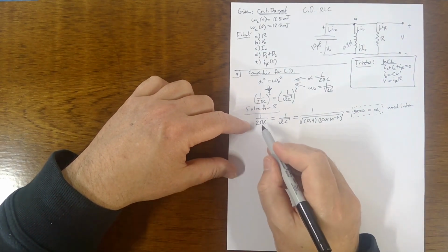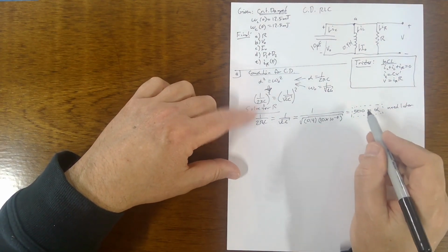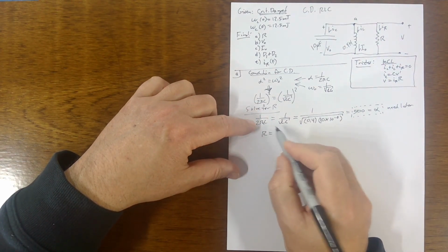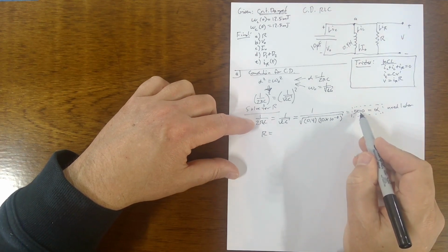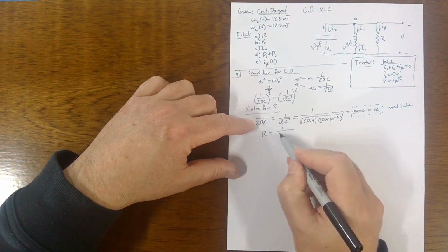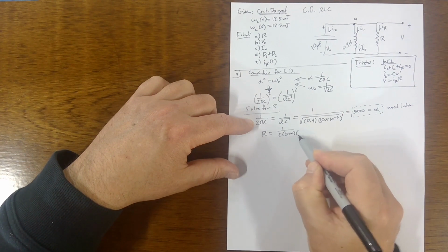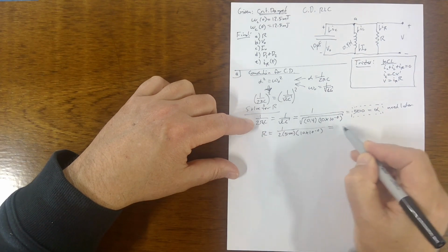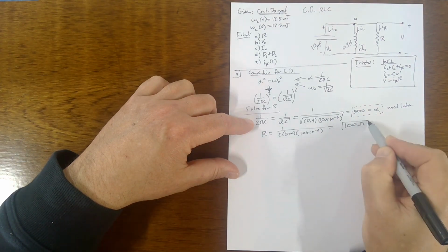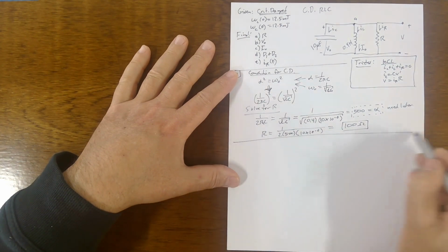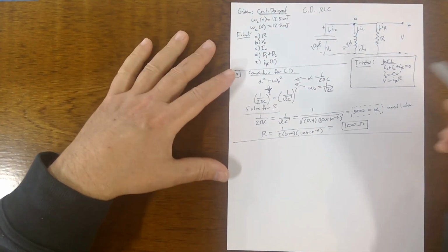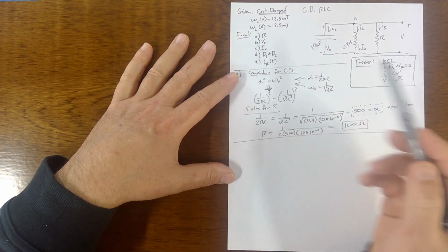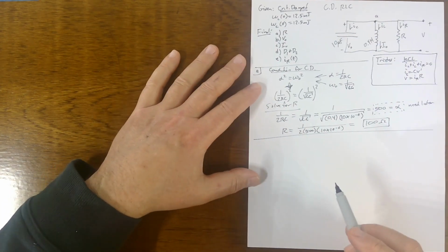All right, so we can go back to the extremes on either side of the equation and solve for R. So R is just swapping alpha and R. It's going to be 1 over 2 alpha C, with C being 10 times 10 to the minus 6. So it's going to be 100 ohms. First answer. Just playing with these formulas that we're given and realizing that this is the condition for critically damped. And then it's just a little algebra puzzle.